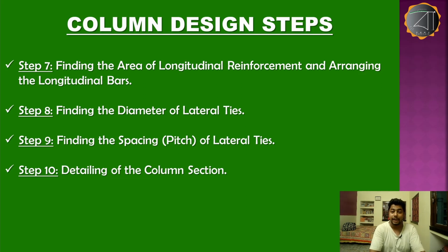And step 10, which is the most vital part: after all this designing, we have to detail the column section so that it can be used by another person in a very easy way by just reading the drawing or the detailing of that section. So these are the 10 steps for designing a short axially loaded RCC column.